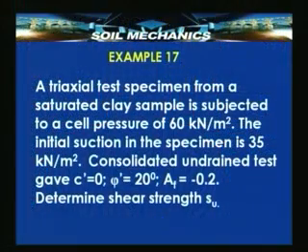Let us take a simple example of the use of the pore pressure parameter. Let me read out the example. A triaxial test specimen from a saturated clay sample is subjected to a cell pressure of 60 kilonewton per meter square. That means a clay sample is taken and a specimen is extracted from that, and it is subjected to a cell pressure of 60 kilonewton per meter square in a triaxial experiment.